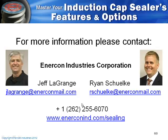Each of the sealing heads is different. With all of our systems that we supply, we do supply a gap gauge that is set to 1/8 of an inch. So if that's the level you want to use, you can use that. If you want to use something more like 1/4 of an inch or 3/8 of an inch, just simply put a few of those together and establish that to get the right gap there. What's important is that it's consistent, and that every time you set up that is a consistent number. It is a topic that we do cover in our operating window webinar in more detail.